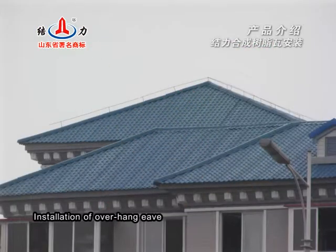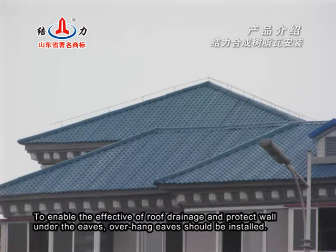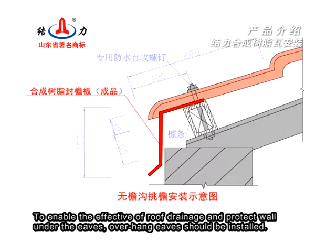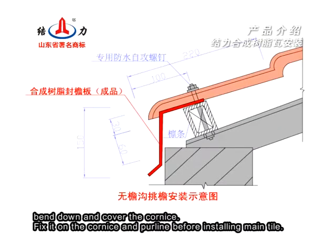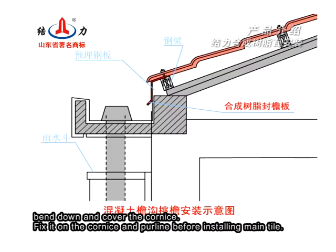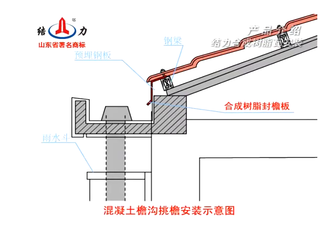Installation of overhang eave. To enable effective roof drainage and protect the wall under the eaves, overhang eaves should be installed. Metal and synthetic resin sheet are a better choice. Put it in 100 mm from the eave edge. Bend down and cover the cornice. Fix it on the cornice and purlin before installing the main tile.